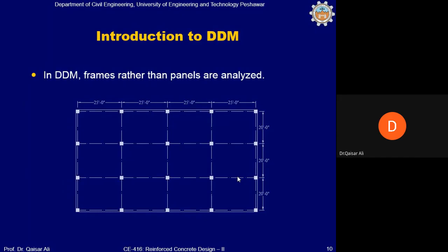Generally speaking, a slab with beam system is an economical system. Slab without beams will be an expensive system because the weight will be more, and the reinforcement to be provided within the slab will also be a little bit more than in the slab with beam system.